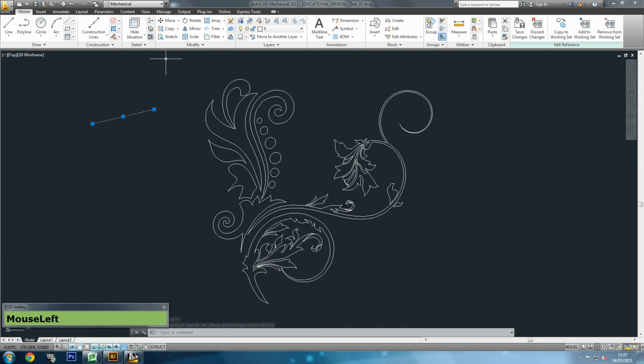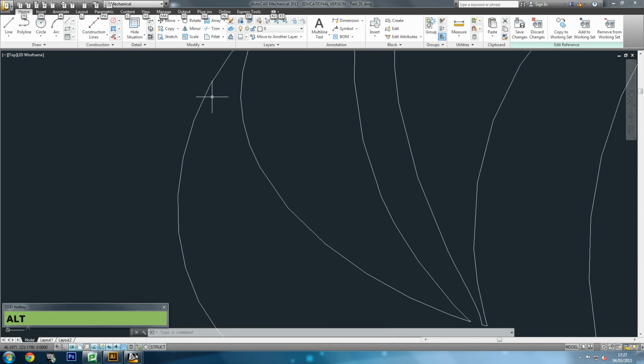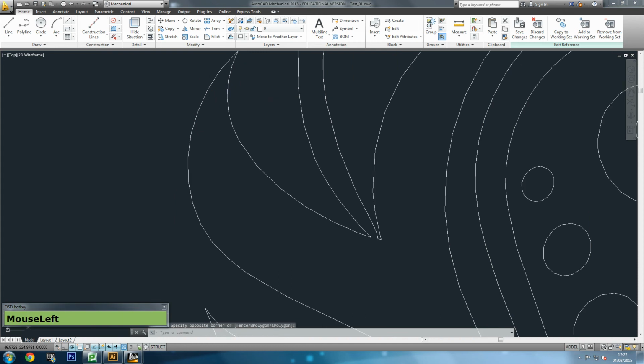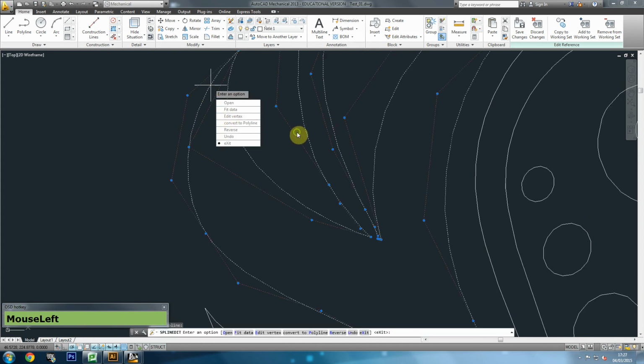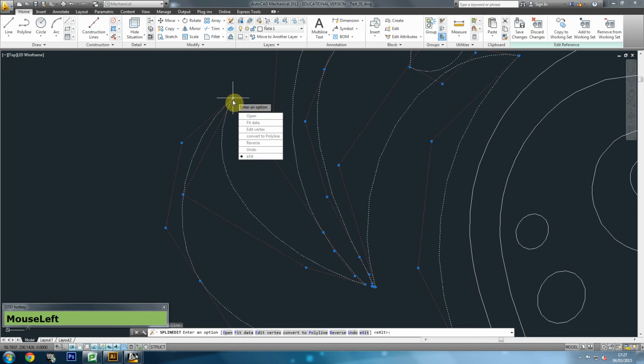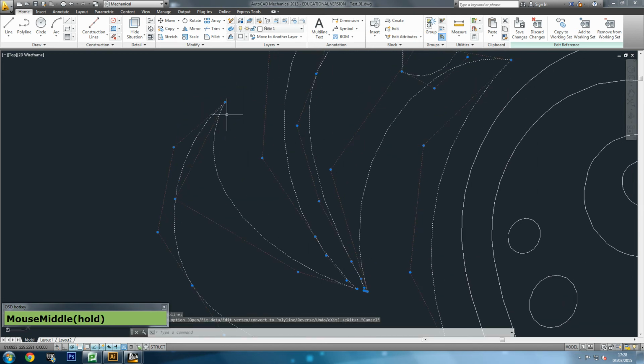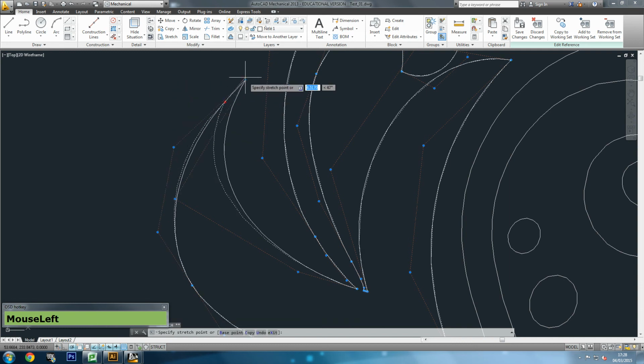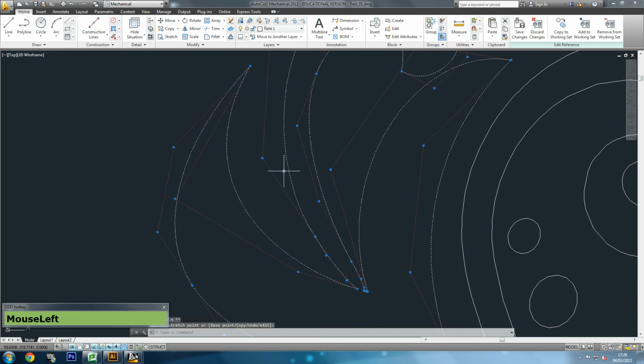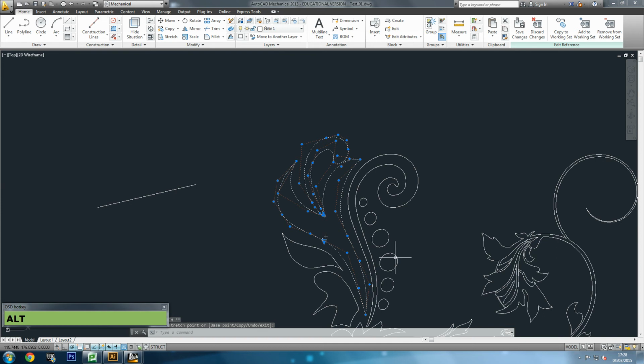Once we import everything from Illustrator into AutoCAD, AutoCAD would automatically convert everything into generic and native AutoCAD drawings. So for example, I could zoom into here, and if I didn't like how this line looks, I could select it, and I could get one of the points and change its position to somewhere else and make any changes that I want.